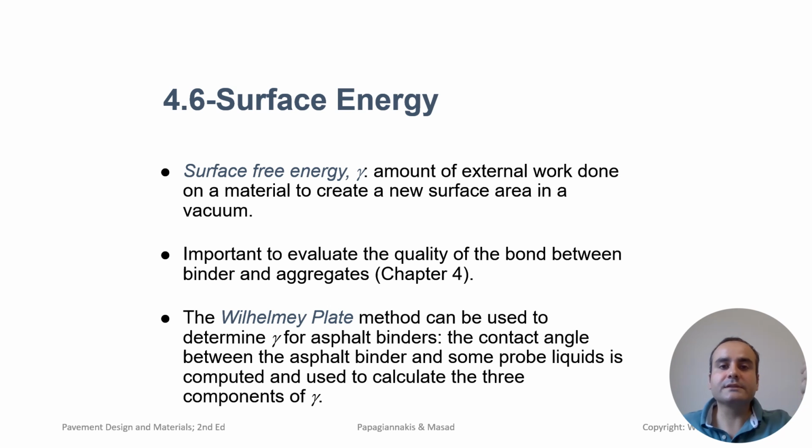High cohesive surface energy increases the internal strength of the binder, improving its resistance to cracking and deformation. Surface energy in general plays a critical role in moisture sensitivity and overall pavement durability by ensuring strong bonding between the binder and the aggregate and resistance to moisture damage. There are different techniques and methods to measure the surface energy.